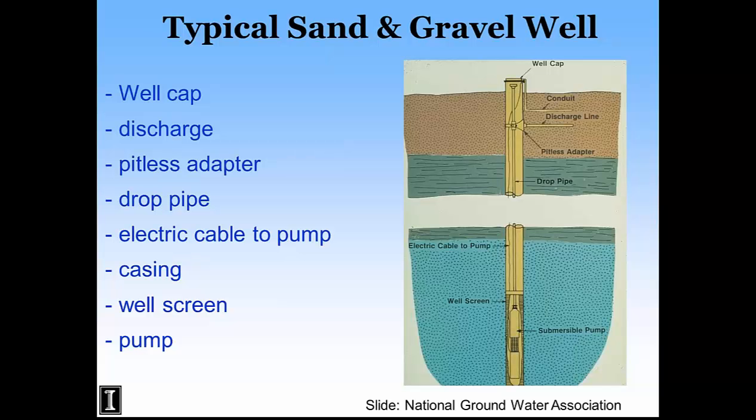And the old style of doing that would be to have a pit around your well. And there was no pitless adapter, so you had a pit, and there are still a lot of those in existence today. They're really a problem. If you have a well that's in a pit, you should talk to a well contractor and find out what it will take and get your well brought up to code. There's no legal reason that you have to do that, but there's a lot of safety reasons. Later in one of the lessons, we talk about abandoned wells and wells that aren't properly sealed and all the problems and safety issues with well pits.